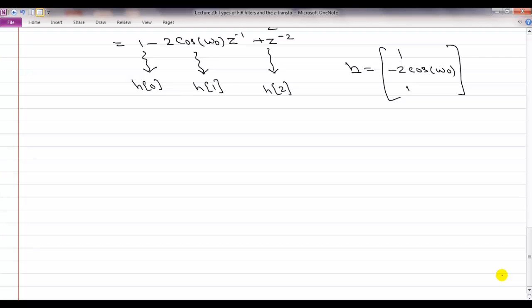In many cases, you would be interested in what I call specialized filters, which is that they don't really have a nice shape. They are sort of a random shape, random in the sense that it can take arbitrary shape. And you are interested in how do I implement that kind of a filter? Well, the only way to do that for specialized ad hoc filters is there is no systematic manner. The only thing you can do is actually really, literally just play with zeros. You just move zeros around, okay? It's like an art that once you have enough insight, someone comes and says, I want this kind of a shape, you're automatically aware that, okay, if I place zeros around this region, this is what it will look like, and then you just wiggle around and you get the right shape.